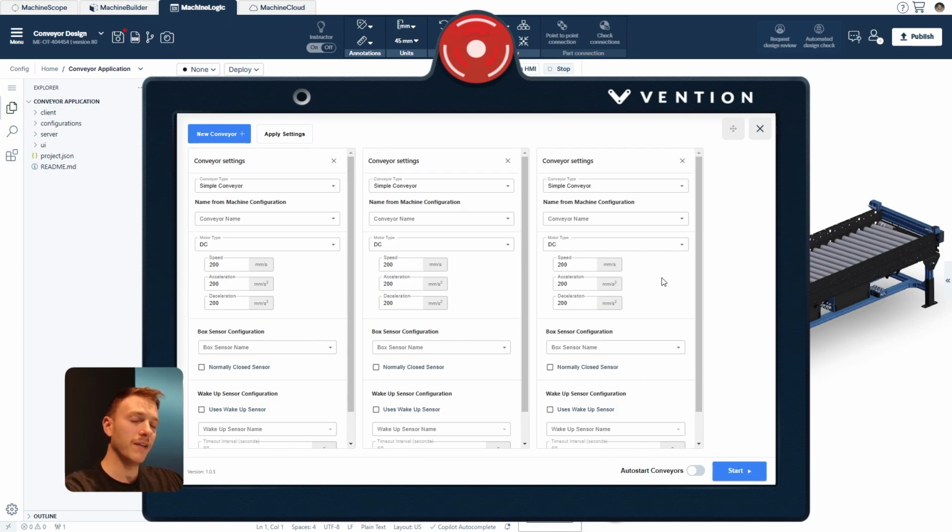Now the behavior that we want is for the end portion of our conveyor, the one on the right over here, to be the leader, and the other 2 sections to follow its actions. So if it's on, the other portions will run, and if it's off, the other portions will stop. So we'll program first the rightmost section, which will be skew zone 2.